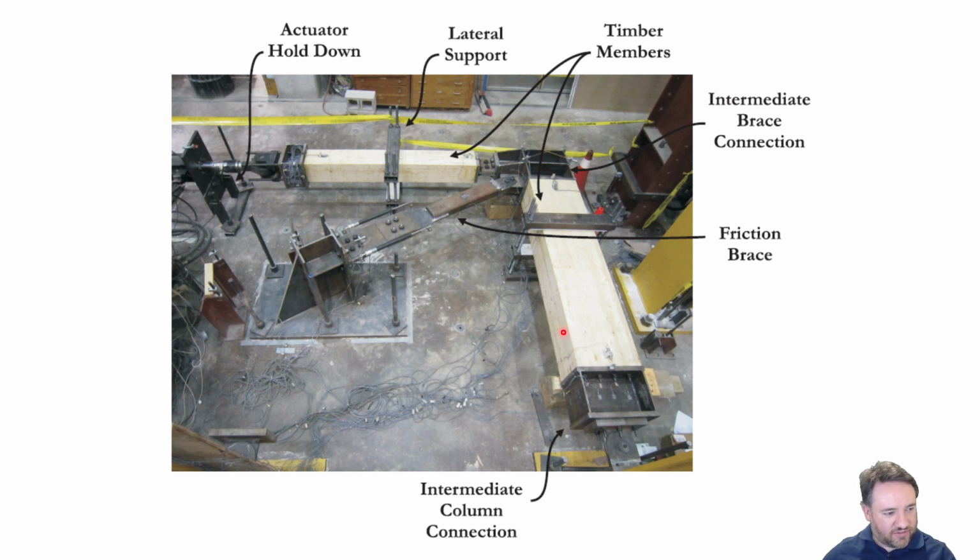So I don't have to go up the side of this glulam member at all with a big steel plate, like I did in the screwed connection. Here I have these end glued-in rods that are providing the reaction, and providing this intermediate brace connection, where our goal was to test an advanced earthquake brace, and how we could practically install that into a heavy timber building. So we used small amounts of steel at select locations to do that, and we instrumented all these interfaces to see how those glued-in rod connections were faring, which was very, very good. Actually much better than I even thought.